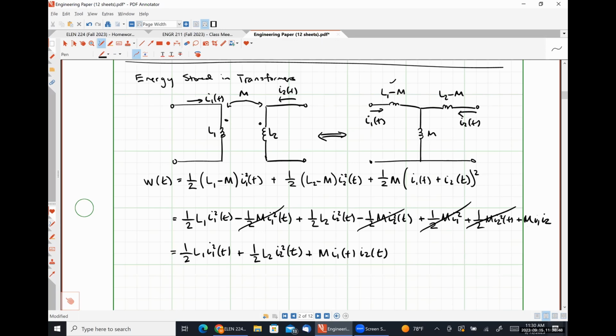So if we flip this whole thing over, the currents are still flowing into the dotted terminal, so it's satisfied. If we change the direction on one of these, it's effectively the exact same thing as changing which side the dot is on. Look at the dot.